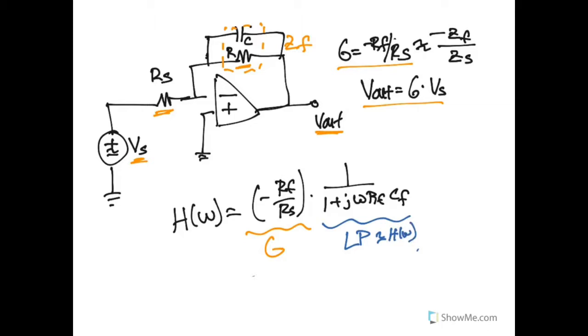And so what it tells us is that in a circuit that looks like this, we've got 2 main parameters that we can work with. When we modify one of them, we can change the amount of gain on the filter, and when we modify the other, we can change the cutoff frequency. So we have two independent parameters that we can adjust.